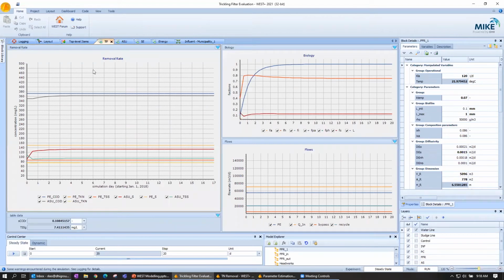So we noticed that the way it's set up now is hardly doing anything. It's taking out 10% of soluble COD from the primary effluent and converting that to active biology. And from operator reports, that's just not accurate. So after a lot of trial and error and reimagining this model, we found that this diffusion coefficient for oxygen, and the one for soluble substrate as well, into the media bed was too low. So if I change that, and these are assumptions that we need to check, right?